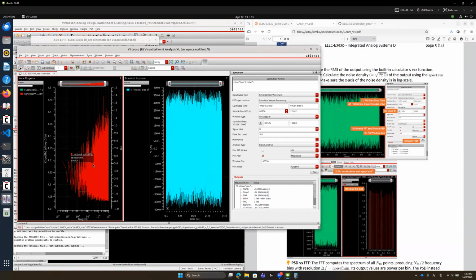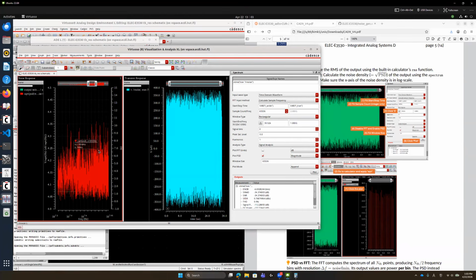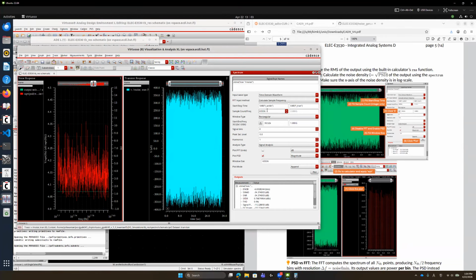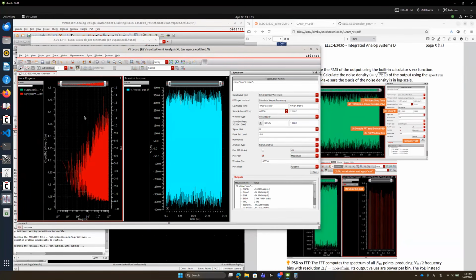Then you can see this. It is very much fluctuating. So this is because the number of data points is a bit limited, even if we are running a very large amount of FFT points here. So in this case, what we can try is that we are computing this chunk and this chunk. Let's say this is 50% of data points. This is 50% of data points.